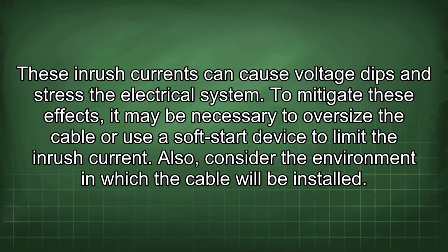These inrush currents can cause voltage dips and stress the electrical system. To mitigate these effects, it may be necessary to oversize the cable or use a soft start device to limit the inrush current. Also, consider the environment in which the cable will be installed.